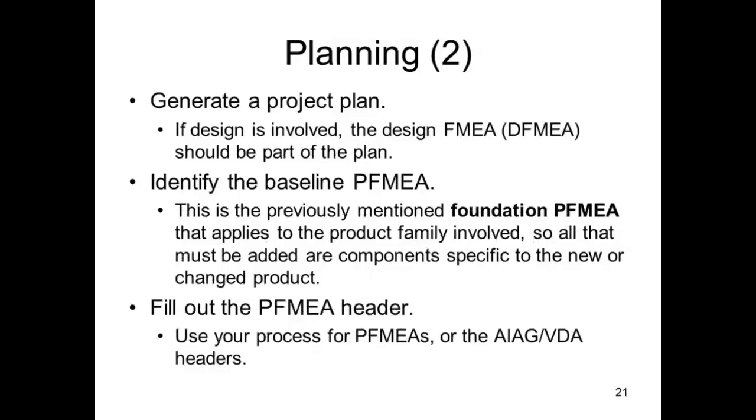Generate a project plan. If design is involved, the design FMEA should be part of the plan. Identify the baseline PFMEA, which is the previously mentioned foundation PFMEA, especially if we have a product family and group technology. That can be helpful because group technology applies to all the parts in the product family, so all that must be added are the components specific to the new or changed product. Fill out the header, which is probably going to be unique to your organization and pretty much routine.